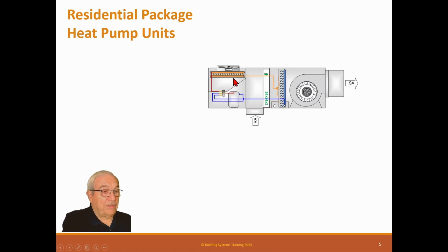But a couple of minutes is enough to send a cold gust of air down through the space, so they put a strip heater in there to get rid of that. So again, it has the same thermostat lugs as the other unit, same subbase. However, if it's a heat pump, it has to have a special subbase.